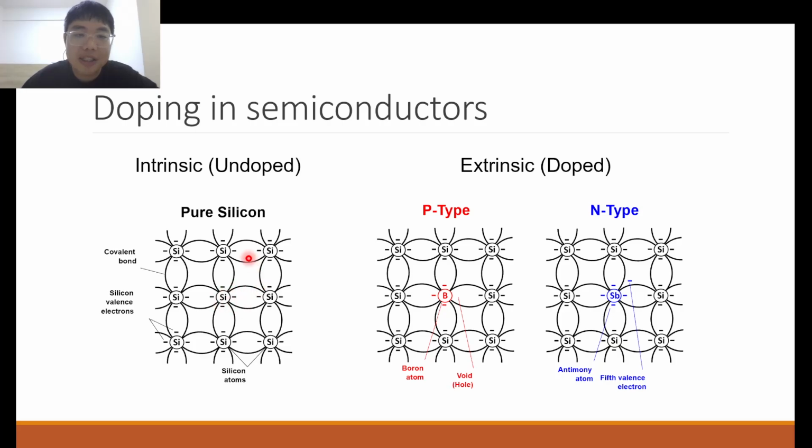Silicon has this structure over here. We have 4 covalent bonds formed by each silicon atom with the neighboring silicon atoms. Actually, it's a tetrahedral geometry, but for the sake of drawing it in a 2D diagram, they just draw it like this. So let's just treat this as an illustration. We see that the electrons are localized in the silicon-silicon bonds. They are fixed there. You do not see the case like in a metal where there's a sea of delocalized electrons free to move. No. The electrons are fixed in the silicon-silicon bonds.